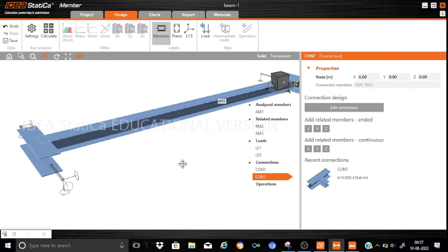So in this case, remember, the buckling effects are not relevant to us. Here we will not do any kind of LBA, or the buckling analysis with imperfections, that's the GMNIA. We will perform only one analysis, the material nonlinear analysis, because for a restrained beam, buckling is not relevant to us. So we have to go straight to the calculate button.